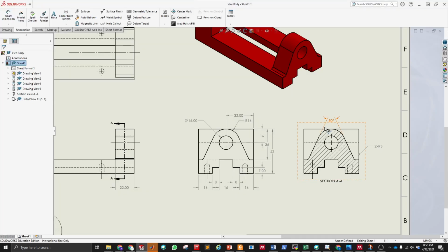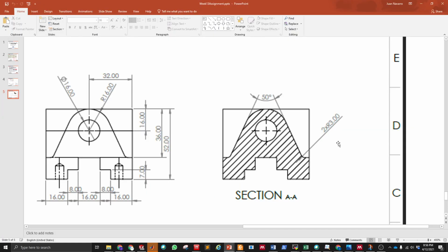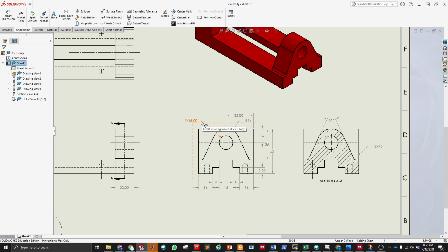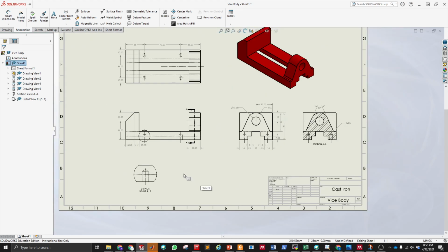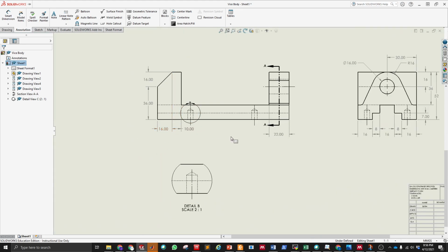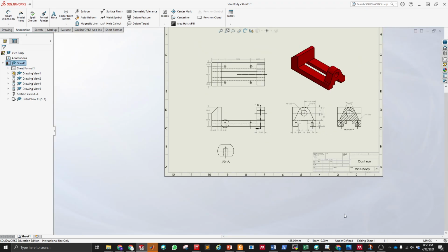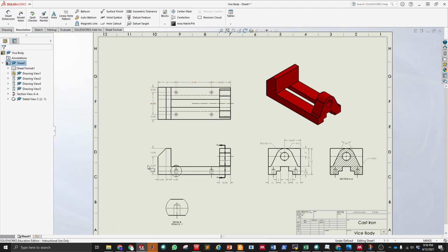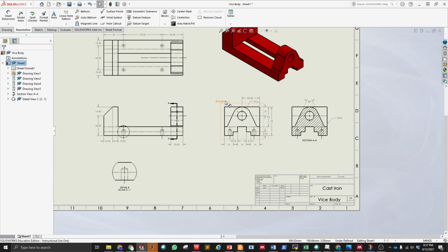like this. So don't worry if you see that in my blueprint some lines are just straight lines, and in my case I have an angle here. Those are just equivalent, different styles of writing the dimension. The important thing here is that you learn how to add dimensions, how to add the center lines, how to add the center marks in SolidWorks, and then changing those little details is just a matter of playing with the dimension representation.